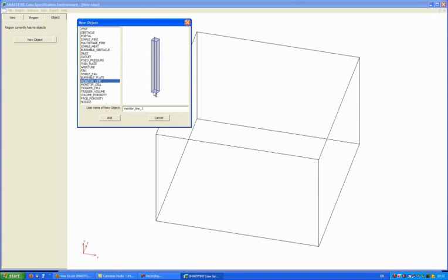Monitor line allows you to create graphs. Monitor cells allows the CFD simulation to output data for specific cells in the simulation. The trigger cell is a tool to allow the activation, deactivation of specific geometry features based on values inside a cell.